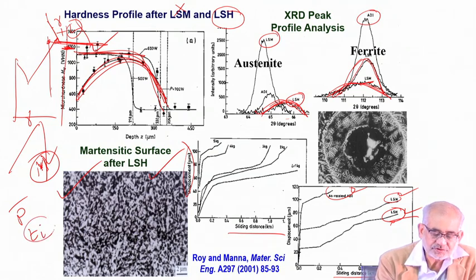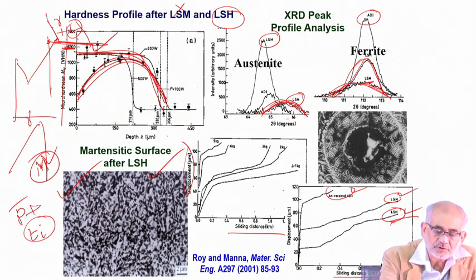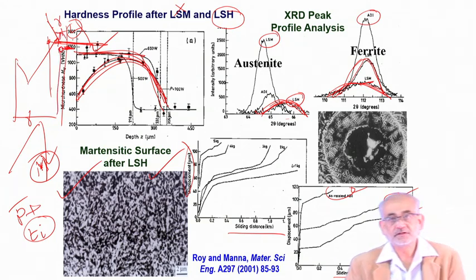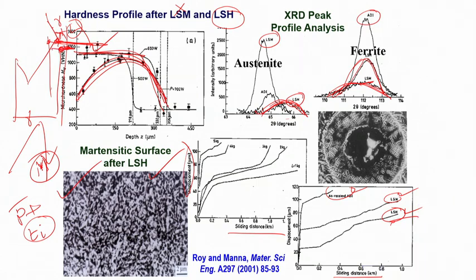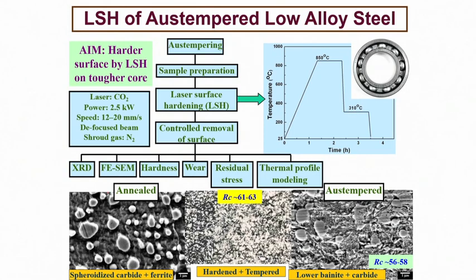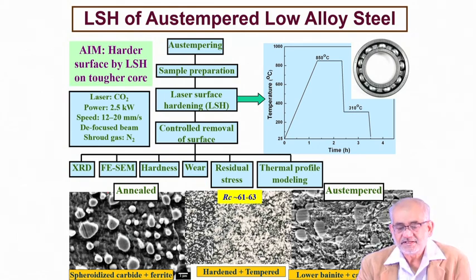So we should heat for a smaller period of time, allow reasonably high power density, and with this combination we should be able to heat only up to this region and not cross this liquidus line, a solidus line, right? So if we heat only up to this region and not go beyond, then we are in all solid condition, and then subsequent self-quenching will produce such a martensitic microstructure. So that's the strategy.